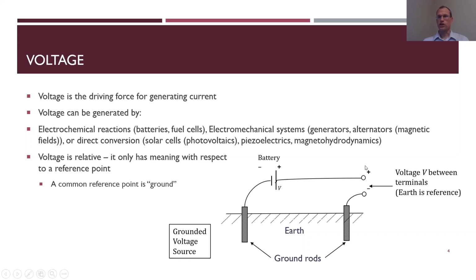And then my positive voltage is whatever I have. So if my battery is 5 volts, then that's what my positive voltage is. So again, some negative terminal attached to the ground, same thing with the battery. So the negative side of my battery is grounded. It's at this reference value of 0, meaning that my positive side is that full 5 volts or whatever it is for my actual battery. It could be 12 volts, could be 1.5 volts, whatever it is.